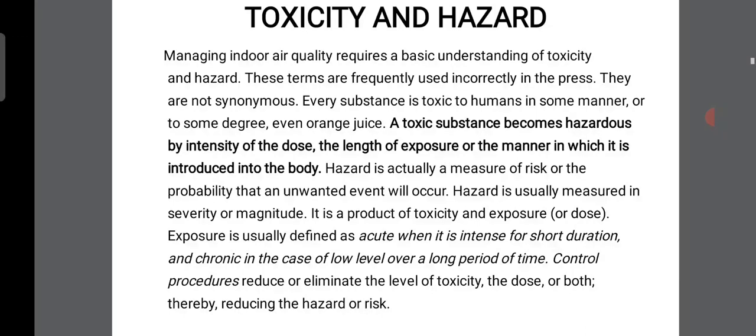Managing indoor air quality requires a basic understanding of toxicity and hazard. These terms are frequently used incorrectly in the press. They are not synonyms. Every substance is toxic to humans in some manner or to some degree, even water or juice. A toxic substance becomes hazardous by the intensity of the dose, length of exposure, or the manner in which it is introduced into the body.